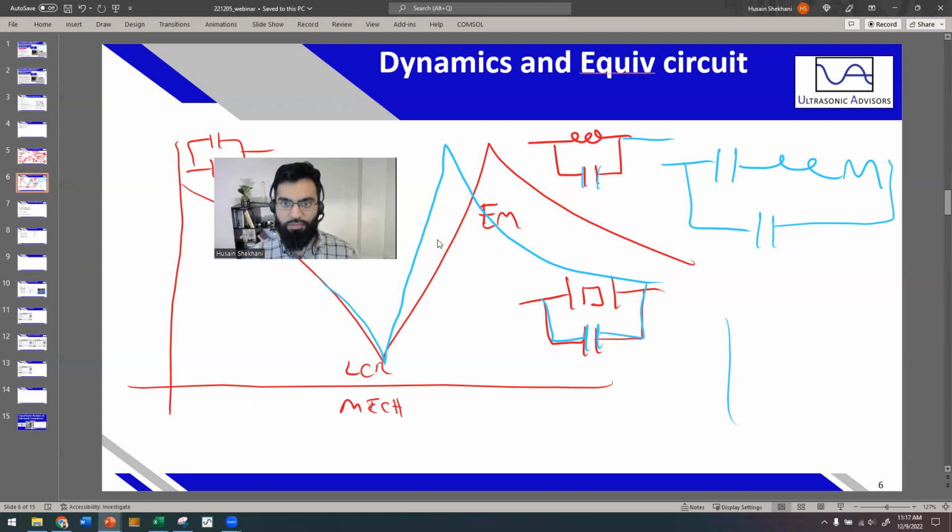So if this value increases, the capacitance will start to increase faster. The current will be more in this case. So it's basically like adding on the capacitor here. The anti-resonant frequency will shift lower, because this capacitive current will grow faster than originally by itself. That's kind of how it shifts. How does it shift the impedance?